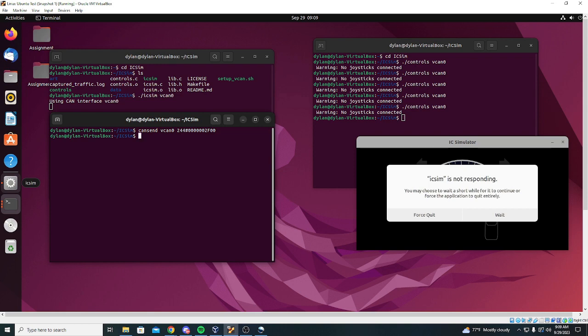This demonstrates how an attacker with knowledge of the CAN protocol and the specific vehicle's CAN message structure can manipulate vehicle behavior. By sending specific messages, we can observe how different systems or devices on the CAN network respond, allowing us to understand their behavior better and test potential vulnerabilities. Tools like cansend, candump, and cansniffer will allow us to analyze, understand, and interact with the CAN network.